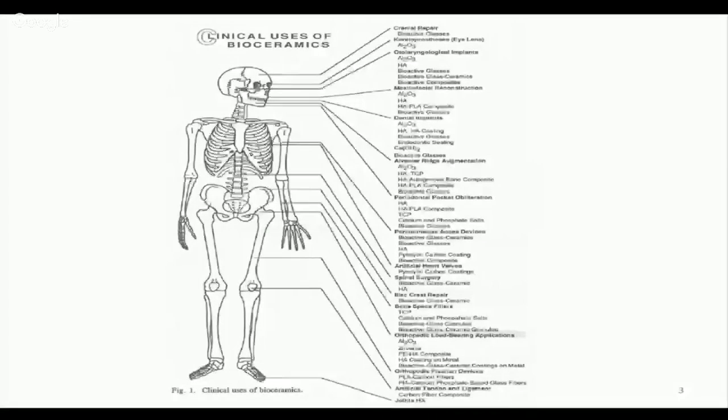For an implant where you want some kind of remodeling, the TCP and OCP are there along with the hydroxyapatite, which doesn't dissolve easily. But as the TCP and OCP dissolve, there is an increase in the local concentration of calcium and phosphate ions. This calcium and phosphate again reverts back as minerals, and then eventually gives you faster bone growth.